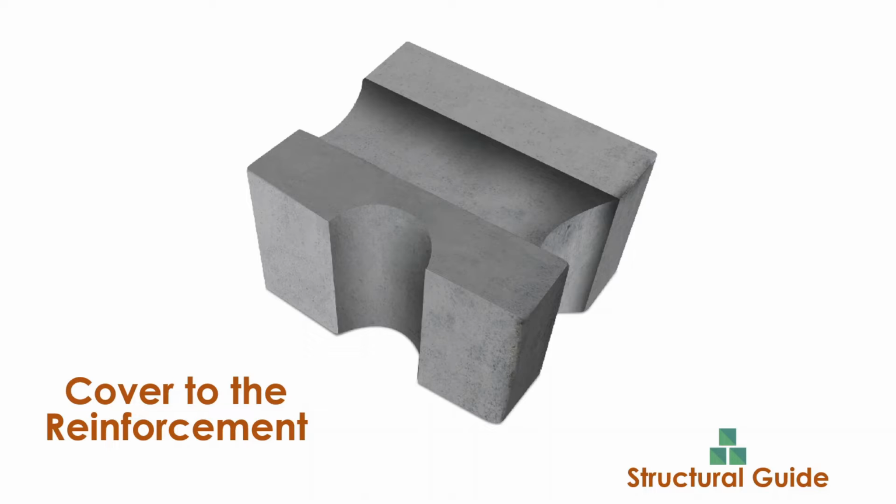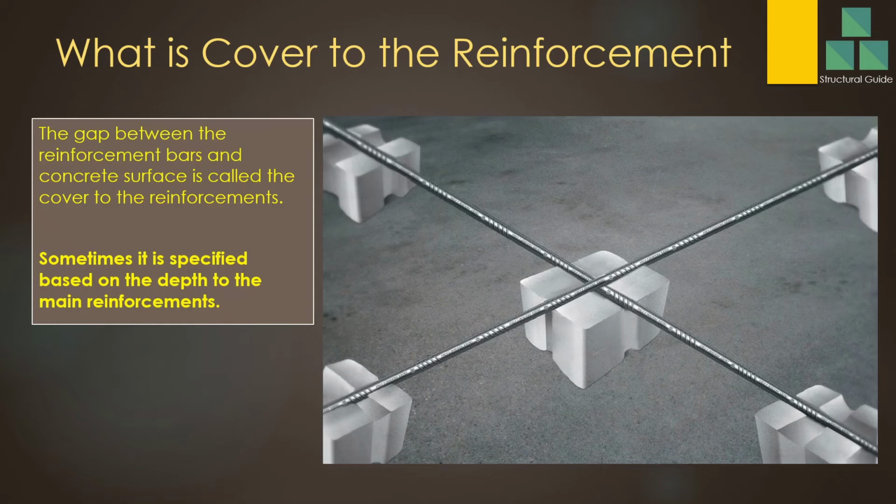Let's discuss cover to the reinforcement. What is cover to the reinforcement? The gap between reinforcement bars and the concrete surface is called the cover to the reinforcement. So this is the reinforcement bar we are talking about. The gap between this reinforcement bar and this concrete surface, this height, is called the cover to the reinforcement.